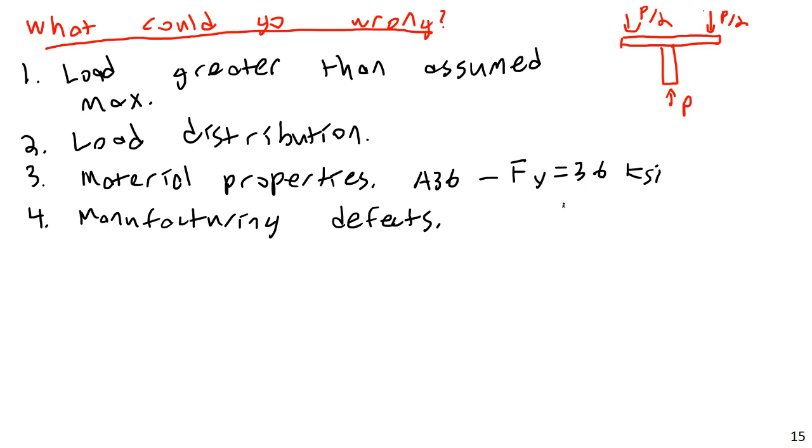You could have a weld, like a fillet weld. Say you have a plate here, and a plate here. Ideally, the way a fillet weld would work, this entire thing will be full. But just looking at it from the outside, you can only see the outer layer. What if there is a small cavity in here?